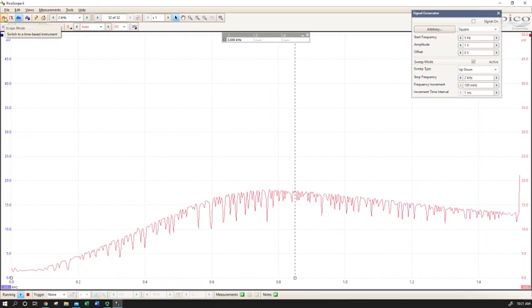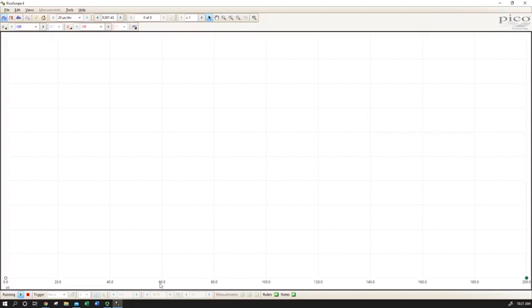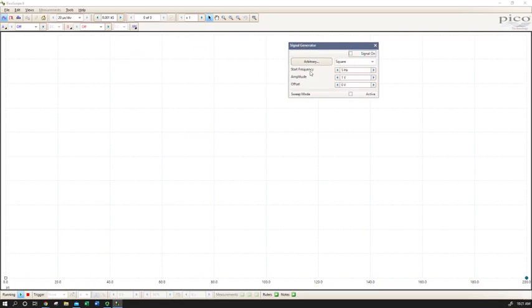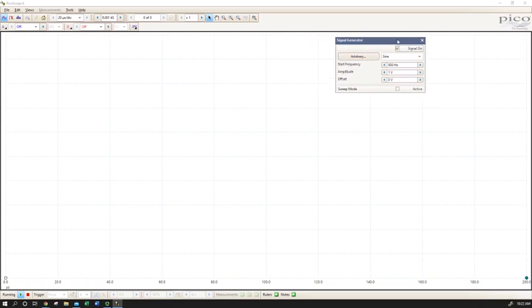To dial it in a little bit differently, we're going to use phase difference, and for that we need to go back to our oscilloscope. So we're going to go up to our push buttons and click the leftmost one and go back to time-based signals. Now we've got our scope displayed. We're not going to sweep the frequency now. Now we're going to use our AWG, and we're going to put it back to sine wave. Let's start with the lowest frequency that we identified with our spectrum analyzer. So we'll go to 800 hertz, and we'll turn it on.